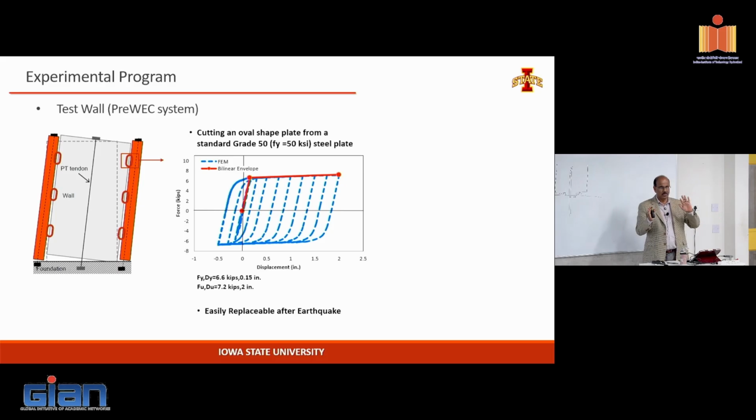So they go through an asymmetric motion. But you can see the hysteresis loop because the steel plates are pretty stable, a large loop. So this loop, for a given displacement or drift, you can figure out how much energy dissipation one O connector would give you. And then you can decide how many O connectors to put in. You can fine tune the design.